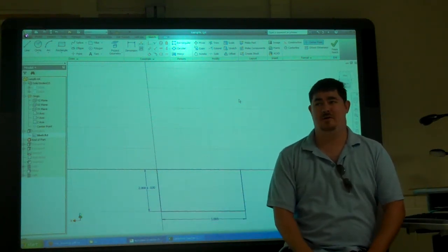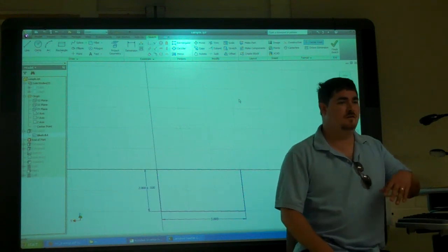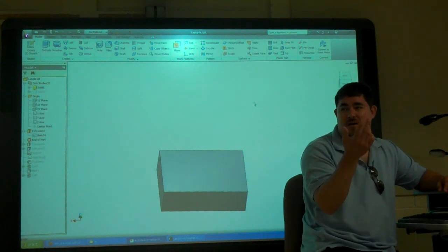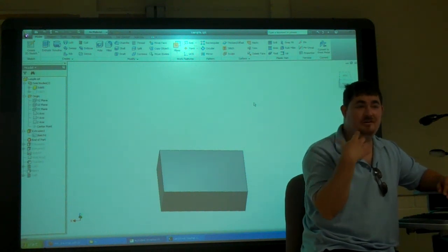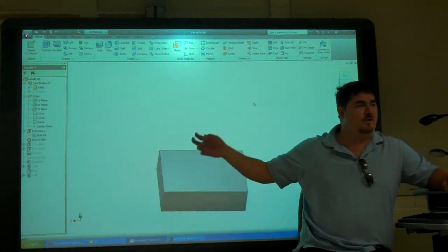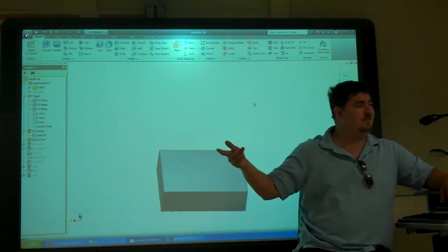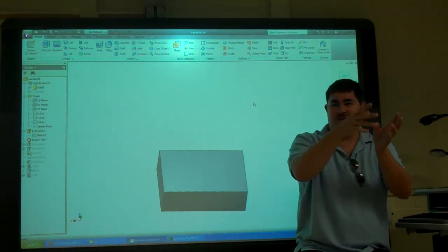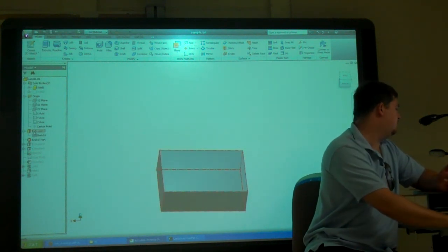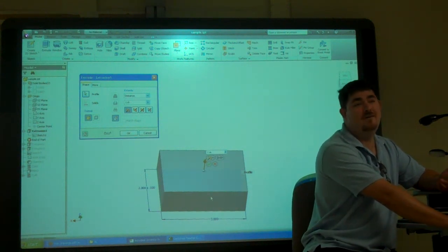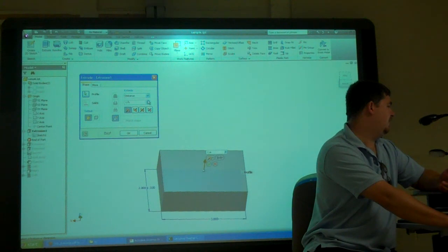Why do you think I'd like to do it here in the model first? Constraint. Yeah, that's the dimension I'm already going to use, but sometimes I might not use the same dimension, especially if I had to use my geometric ones. But if I do it here, I don't forget about it. I don't forget what that constraint is. So when I'm designing it, I think, oh, I need this tolerance here, and I'll put it in there so I don't forget. But some of them you can't do. Here, I can't put a tolerance on that extrusion height. I can't do it.